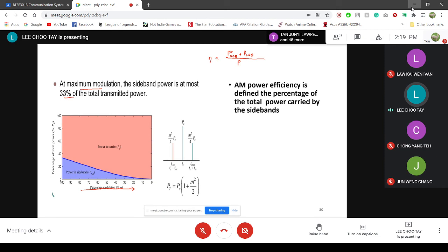It could have some drift, some tolerance. If we do not get the exact 90 degrees, then our theory here will not work. The result of the signal after the phase shifting will not be what you expect. So this phase shifter method, even though theoretically it works, practically it's very difficult to implement.